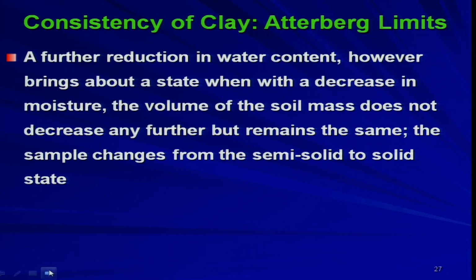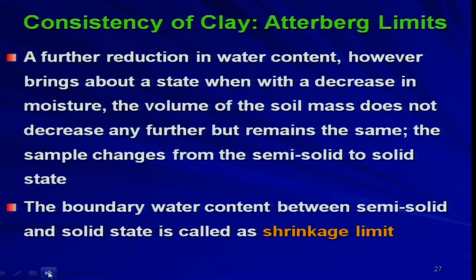The sample changes from the semi-solid to solid state. As I told you, in the solid state, whatever water content you consider, if you reduce or increase the water content, you will not be observing any volume change in the soil matrix. The boundary water content between semi-solid and solid state is called the shrinkage limit. So, this is the boundary between semi-solid and solid state. That means between shrinkage limit and plastic limit, the soil will be behaving as a semi-solid.